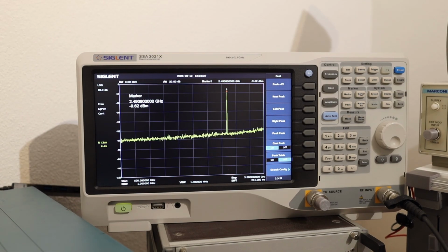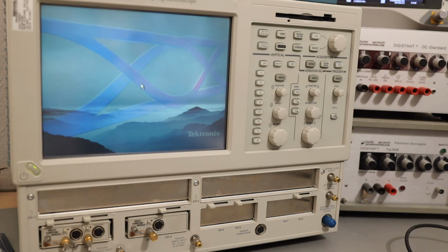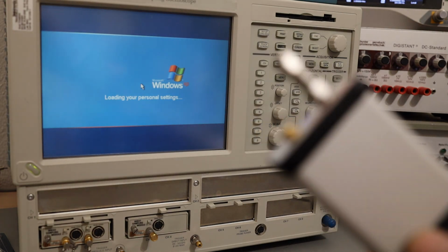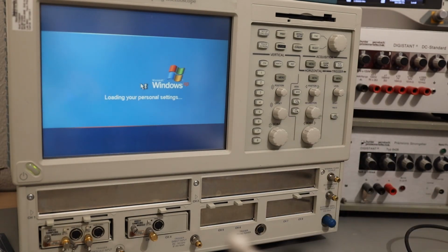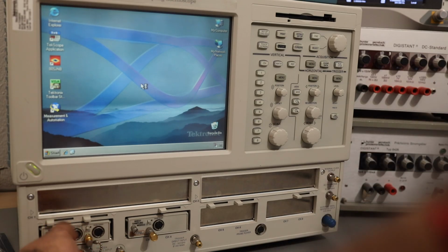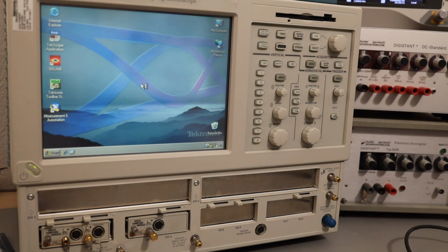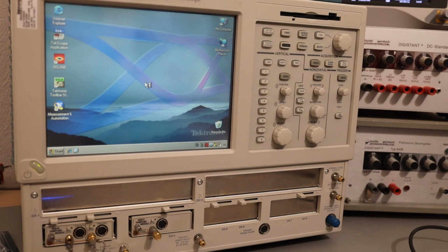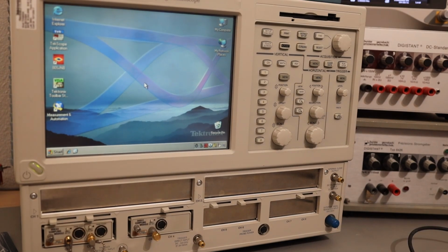So we'll go now to my big oscilloscope, and we will try to see how decently it works in high frequency ranges. To be able to use the device with my electronics, we will use this SMA adapter, and we will connect it to my 20 gigahertz module, and we will see how easily we can operate it. These modules are high sampling oscilloscope modules. They are very sensitive, so we will not be able to feed much signal amplitude into them. Be aware not to feed very high voltages into them. So let's connect them and we'll see.